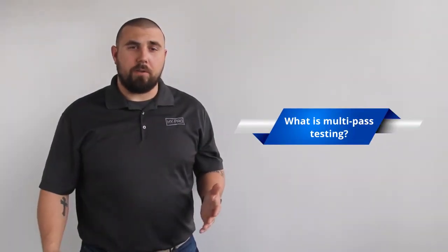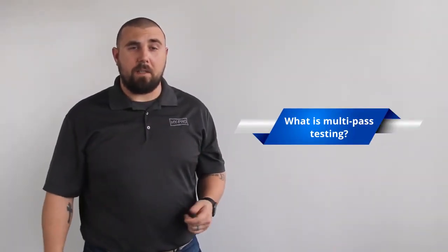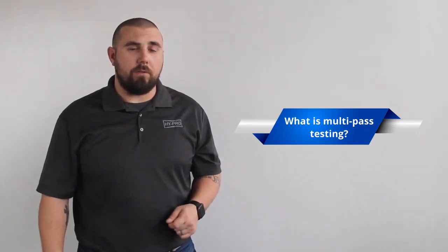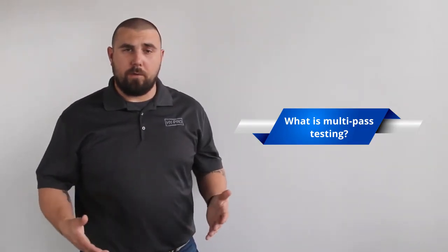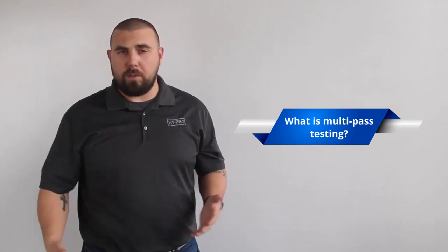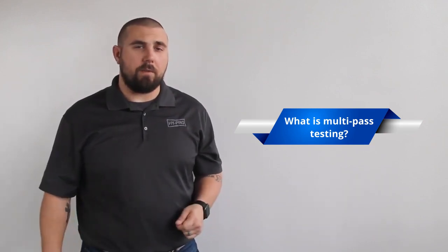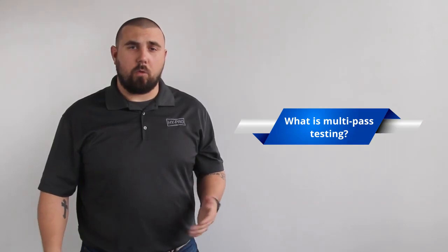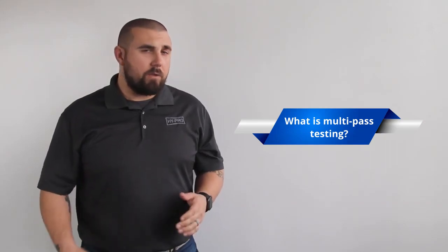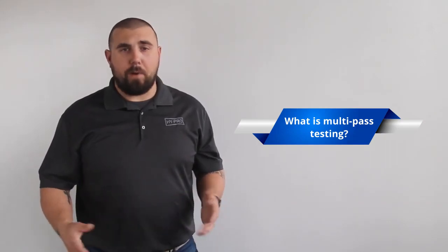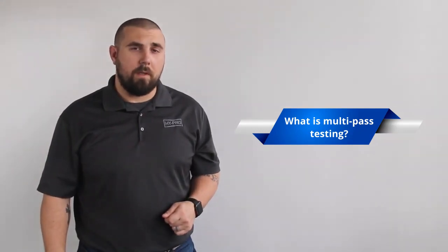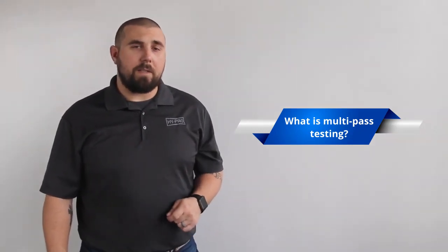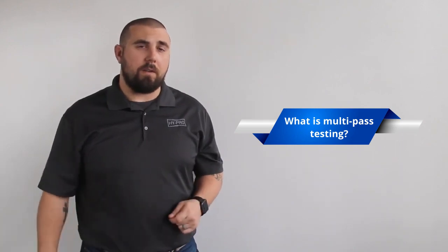Multi-pass testing is a broad term that is used to define the type of testing utilized in the hydraulic and lubrication industry to measure filter performance. It is called multi-pass because the fluid that is used to test these filters is recirculated through the filter multiple times. Multi-pass testing is a controlled laboratory testing method, so it's suited best for repeatability and for the comparison of different filters, not as an example of real-world filter performance. There are four main types of multi-pass testing, which we will discuss at further length in our next video.